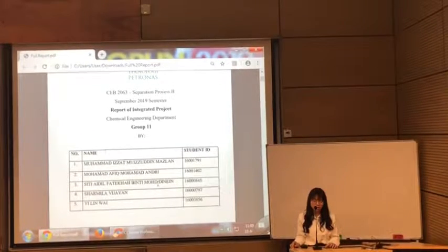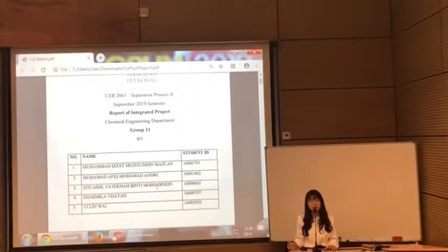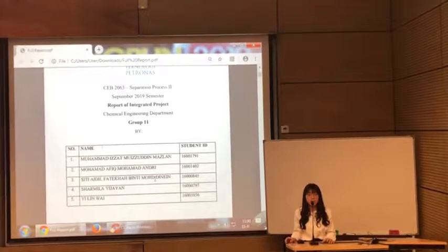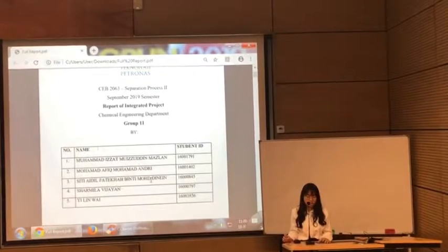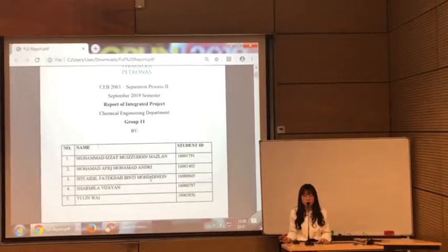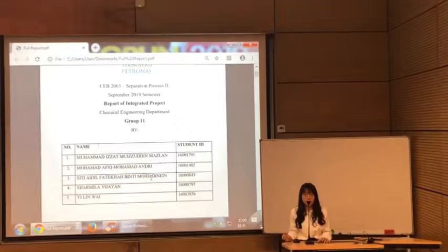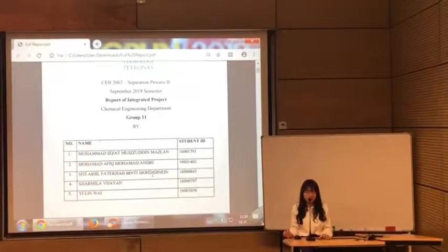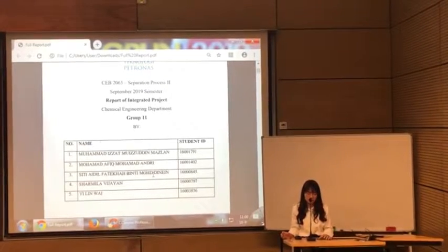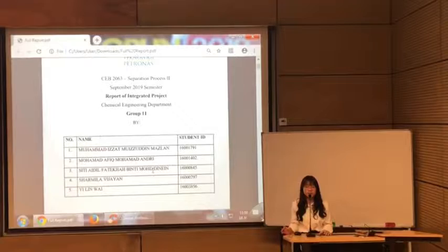This bimetallic catalyst prepared using this method is suitable for the hydrogenation because it will reduce the impurities of 4-CBA to less than 25 ppm, which is 24 ppm. It will increase the selectivity from initially 5.71 without the Sn, to 16.59 with the presence of Sn. Therefore, this is the most desirable catalyst for 4-CBA hydrogenation that won't cause excessive loss of TA and gives a high selectivity and yield of PTA production.